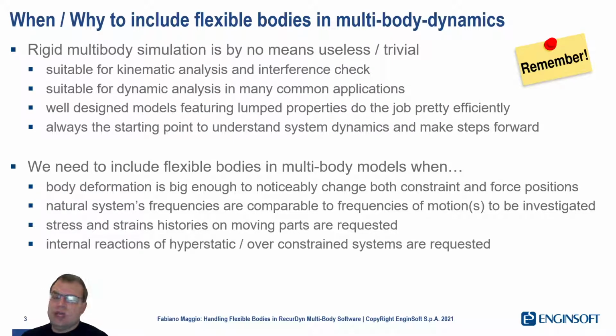The second situation that comes from my experience is when you have vibrations in the system due to natural frequencies of the flexible bodies, of course, and these vibrations are happening at the same frequencies of the motion that you are trying to investigate. The third situation where you might be forced to use flexible bodies is when you are performing multi-body simulation, but you also want to have some structural outputs from your model. Then you have to go for flexible bodies, of course.